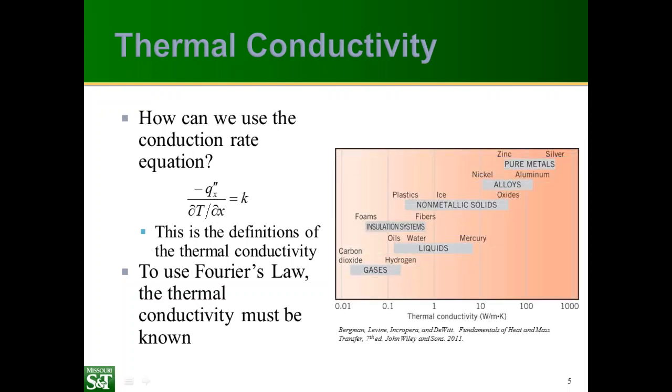And this graph just kind of shows some common ranges for thermal conductivities for various types of substances. Gold and silver, you can see here, have very high conductivity. And in addition, especially gold is very soft, so it can create a more robust contact between surfaces. This is actually why gold-plated connectors are used on high-end audio-video equipment. It produces a more stable, high-conductivity connection.